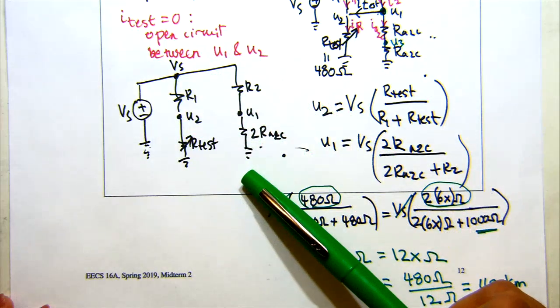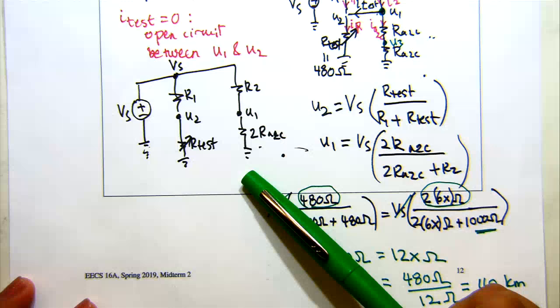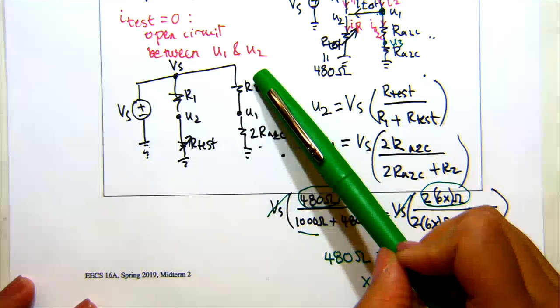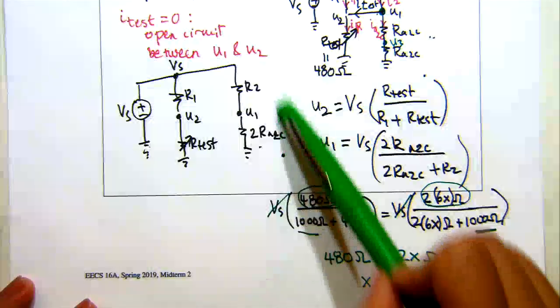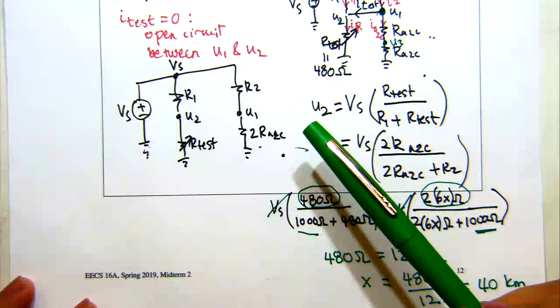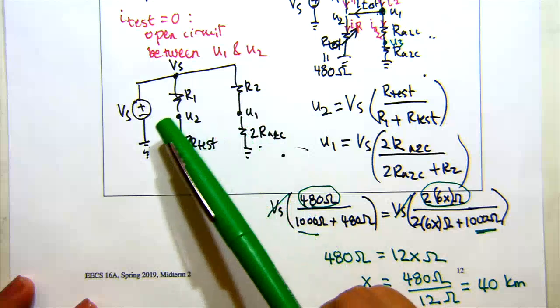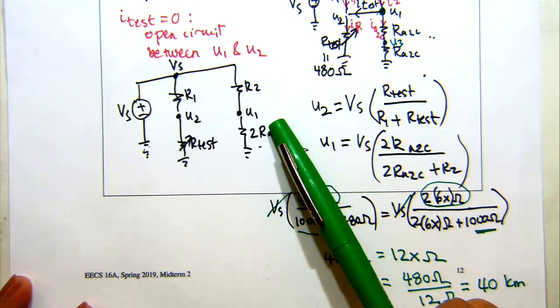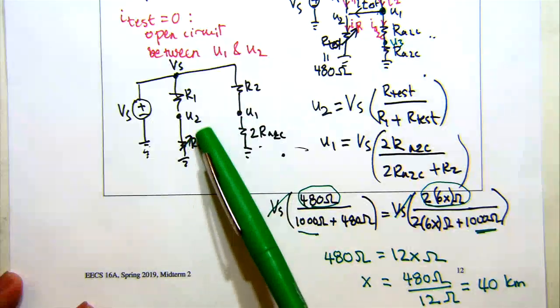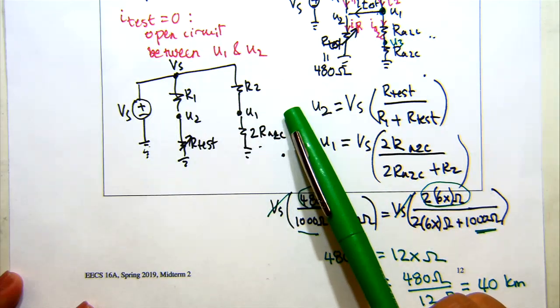Oh, okay. So one thing you could do, if you were to go ahead and calculate the equivalent resistance, you can do that, but the key thing to note here is that you don't want to get rid of U1 or U2. So ideally, what you really care about, right, is the voltage at either U2 or U1.